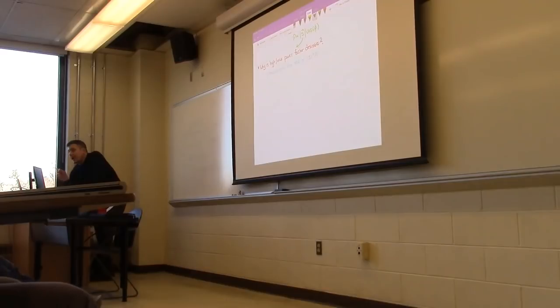The difference is how much benefit are you getting from that loss? It's like I'm going to pay $5 for this. Am I going to get 5 apples that I can eat, or am I going to get 1 apple, or no apple? So that's the difference between out of phase and in phase. When you're completely in phase, you're getting 5 apples back that you can eat. When you're completely out of phase, you're getting no apples. You're transmitting this power, it's all reactive, none of it's usable, and so you're losing power and not using any of it. So the magnitude of the loss, we'll see in a second, is dependent on the magnitude of S, not the magnitude of P.